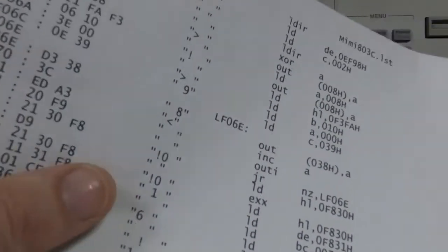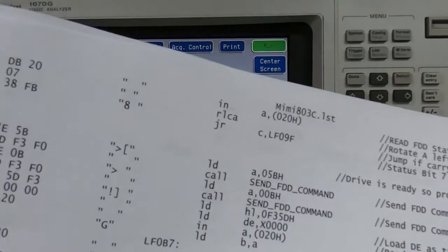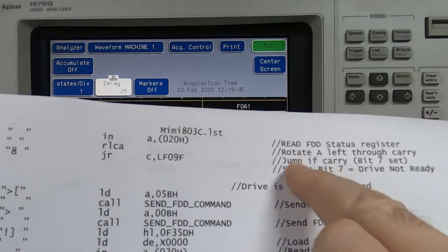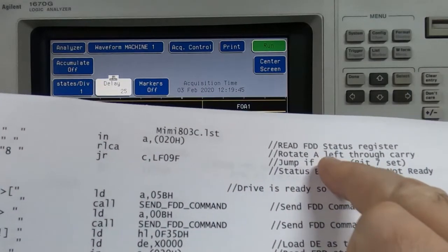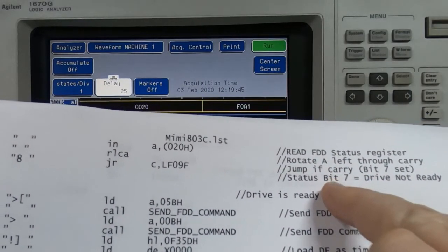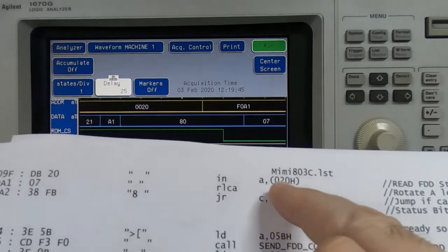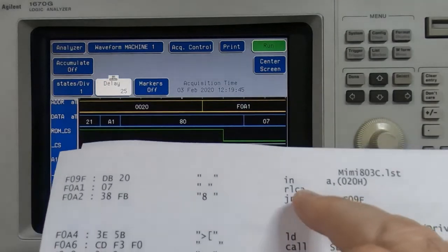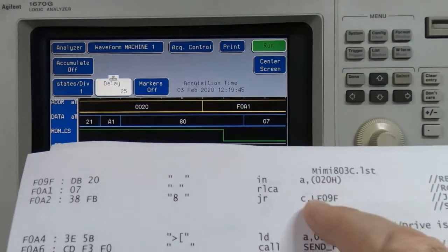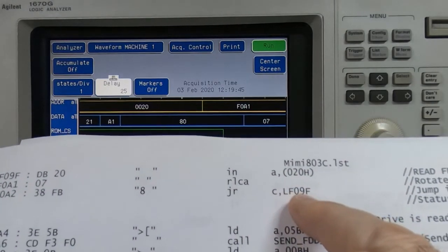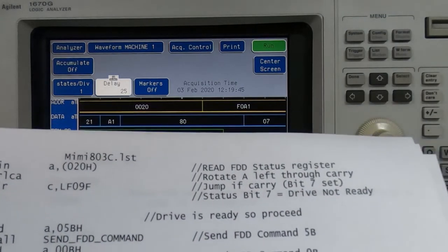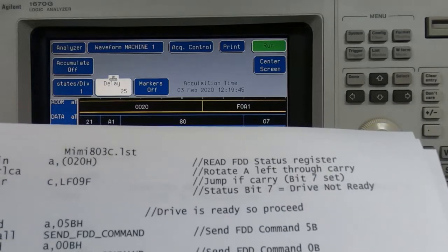And if we then start looking through what's in that block of code, what we can do is go through the instructions one by one, see what they're doing, and then I start commenting on what each particular instruction is doing. I can do this by referencing the data sheet, so I know that, for example, if it's looking for a certain bit value within the status register, I know what it's actually looking for in terms of the drive settings or parameters.